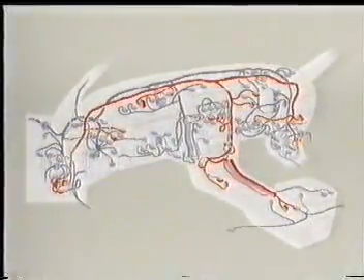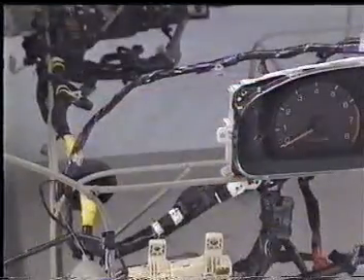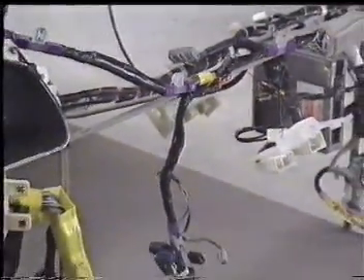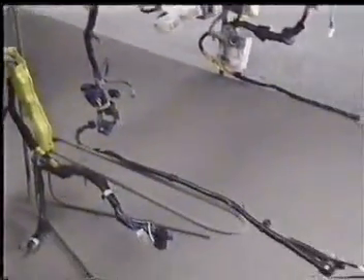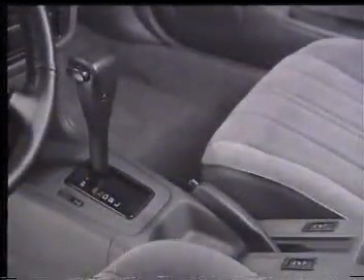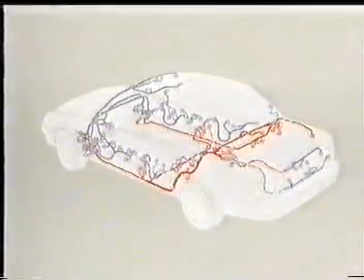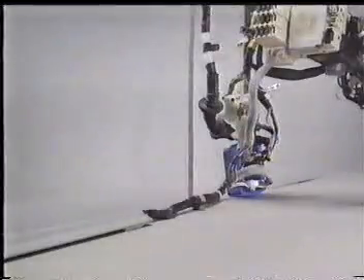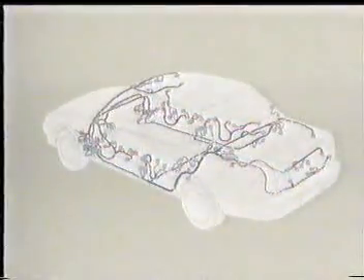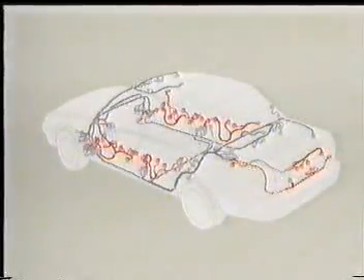The instrument panel wire harness runs from the left cowl to the right cowl, parallel with the cowl wire harness. This wire harness branches out from the center to the center console box. The floor wire harness passes from the right and left cowls to the right and left sides of the floor. Branching out from these harnesses are the door wire harness and the luggage room wire harness.